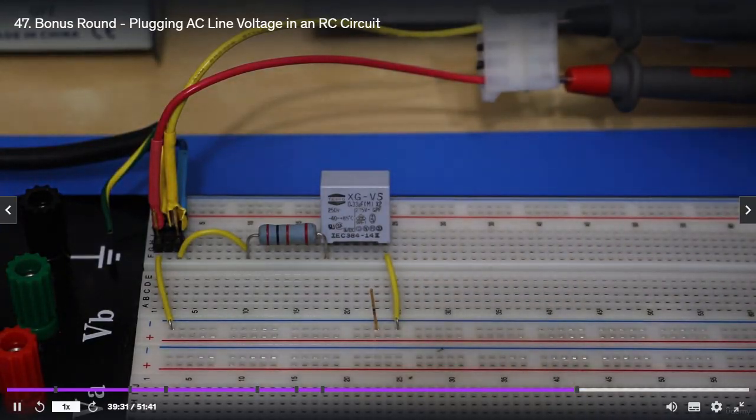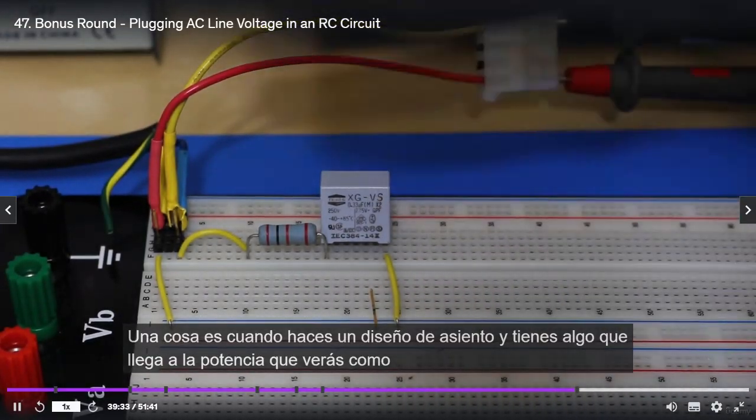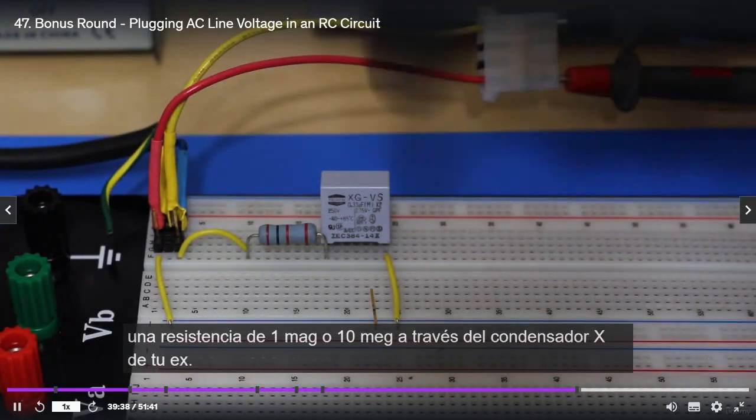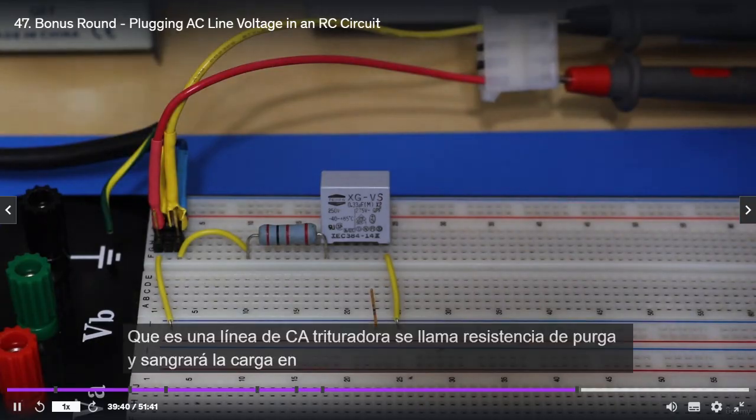Now, one thing is when you do AC design and you have something coming in to the power, you'll see a 1 meg or a 10 meg resistor across your X capacitor, that is across your AC line.